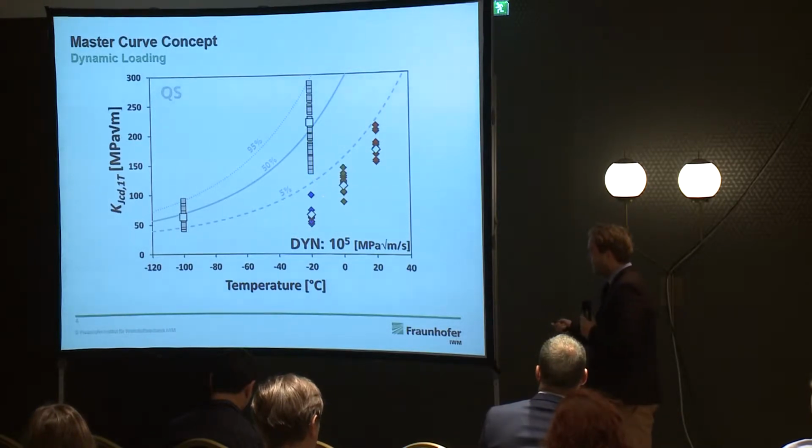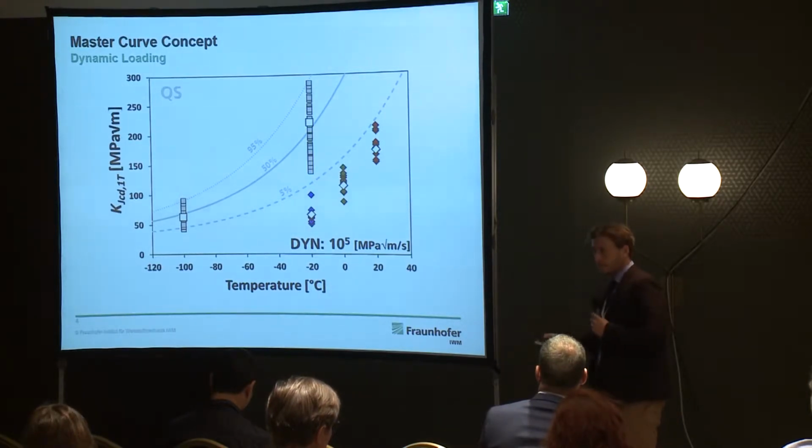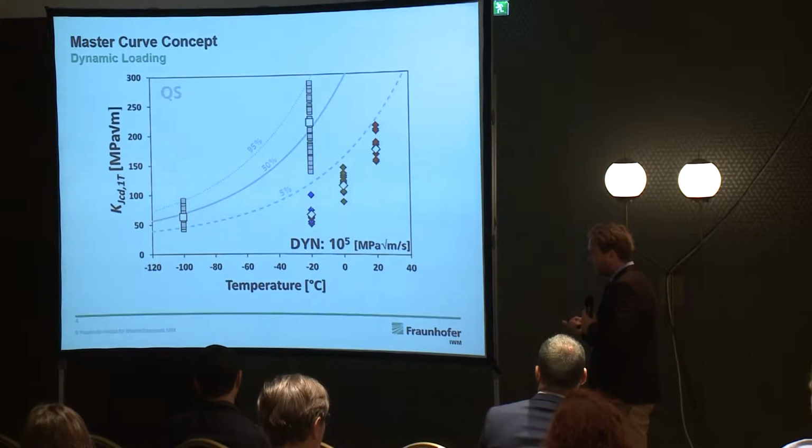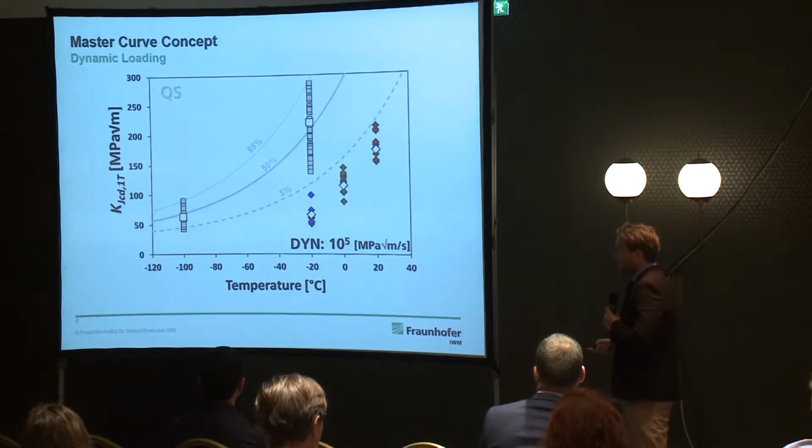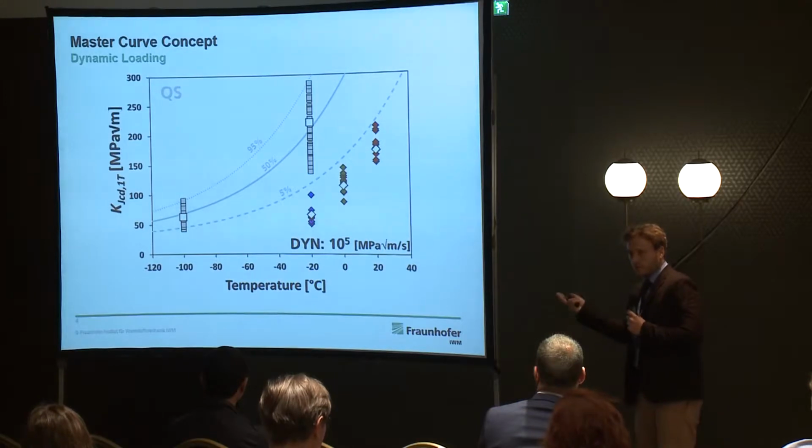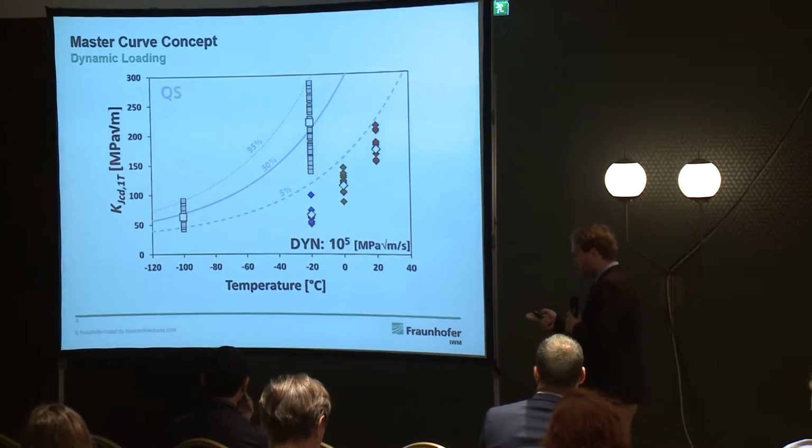We all know dynamic forces cause a dynamic embrittlement, and we end up with a lower fracture toughness value experimentally compared to quasi-static testing conditions. However, if we increase testing temperature, we can still see this characteristic increase in fracture toughness over temperature. So now what's the problem?